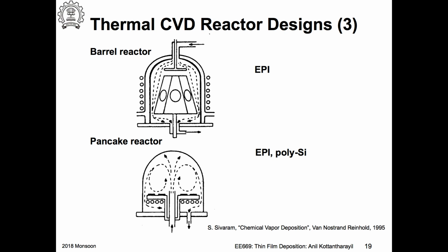So what he's saying is that there is no diffusion through the already deposited film, because you are depositing on top. Okay, so you have something deposited, you are not going to actually have a deposition at the interface. It is going to deposit on top. So there is no need for the reactants to diffuse through the already grown layer. Okay, so the second flux is missing, meaning that's not important.